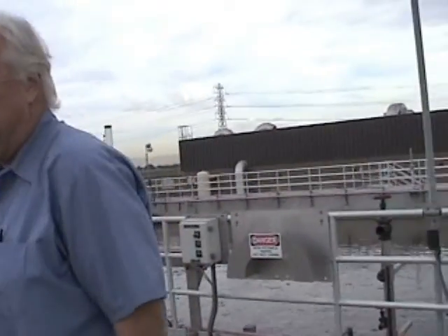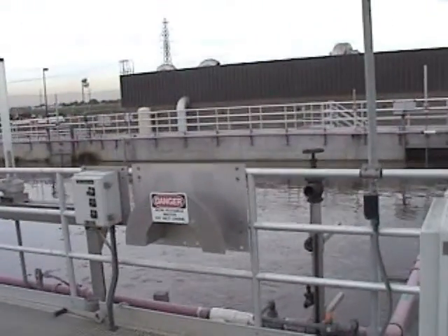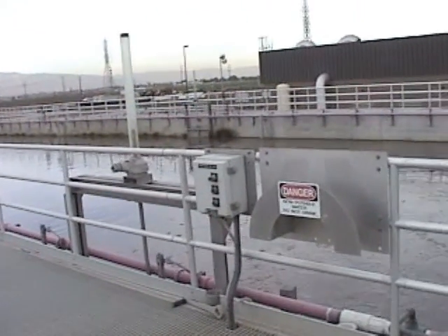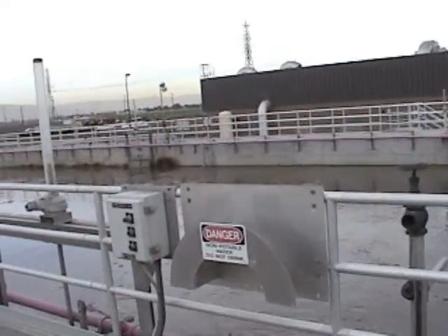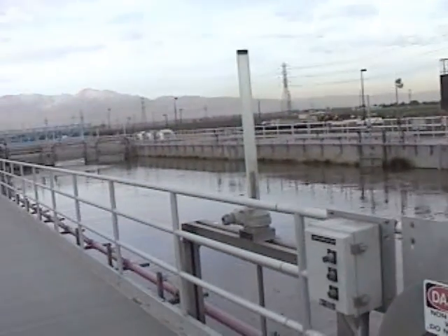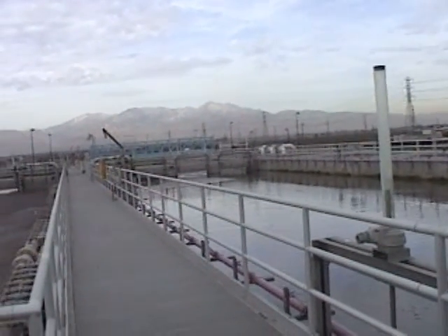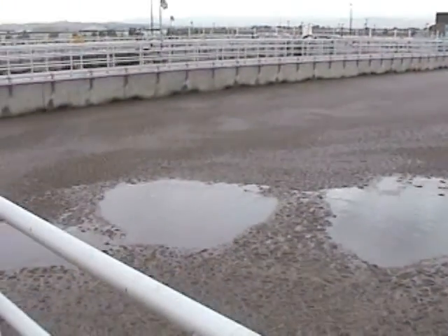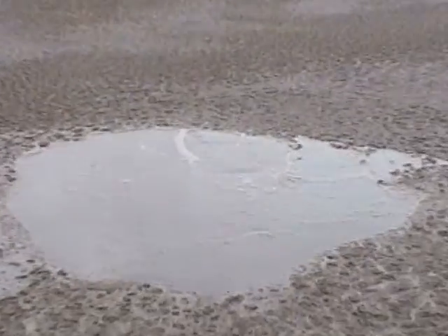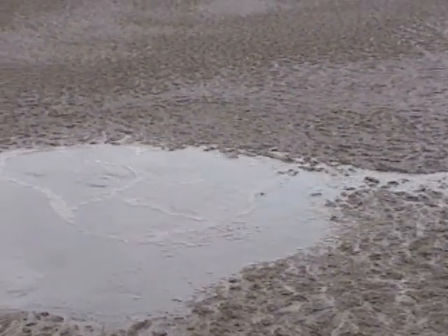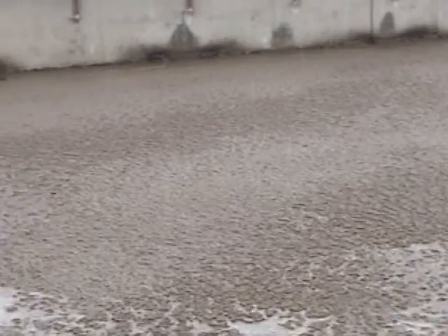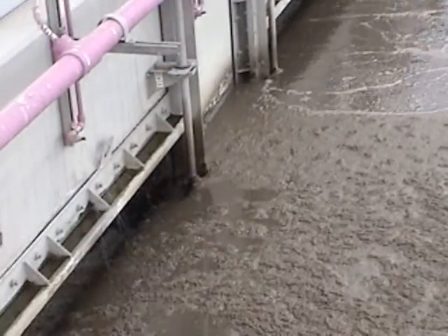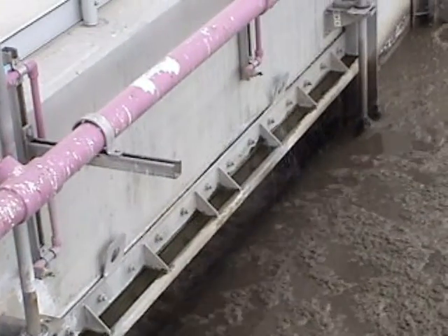Under normal circumstances, I think the DO here is like 3,500. When you're coming up from, let's say, a power outage, and the blowers are first coming on, they're going to try to bring the DO up from like 0.3 or 0.5. You'll see the blower go up to like 10,000 SCFH to bring the DO up. So they have the ability to go quite high, but if the set point is set low, they'll only reach that set point and it may not be enough air.